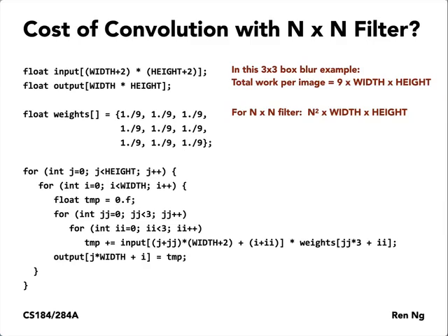In fact, for denoising filters, I'll give you an example. Denoising filters in early digital still cameras, they found practically that to denoise images reasonably, to make reasonably decent looking early digital photos, they needed kind of large filter kernels. The denoising filter might be at a minimum 13 by 13. For image quality reasons, they might have wanted to go larger than that actually. But for engineering reasons, speed reasons, they might want to go smaller than that.